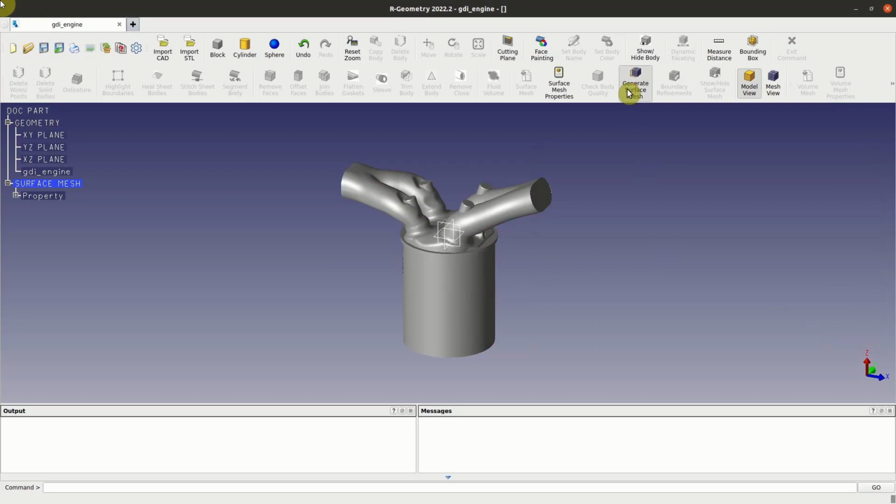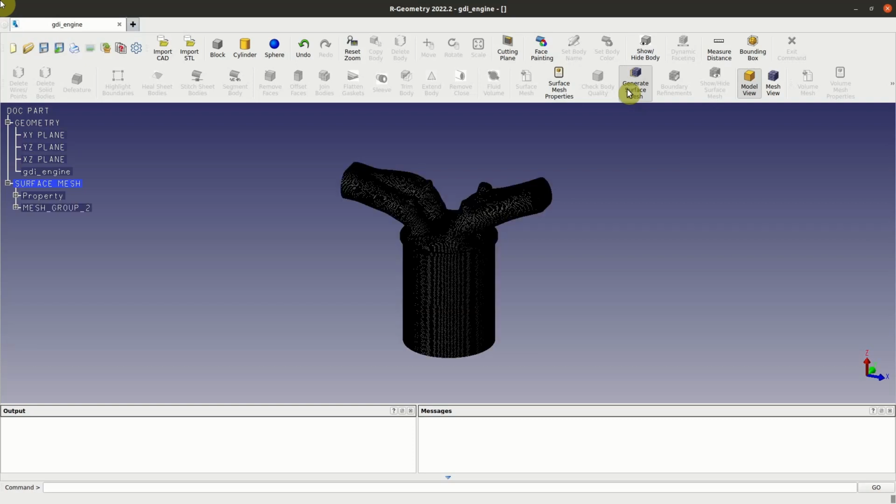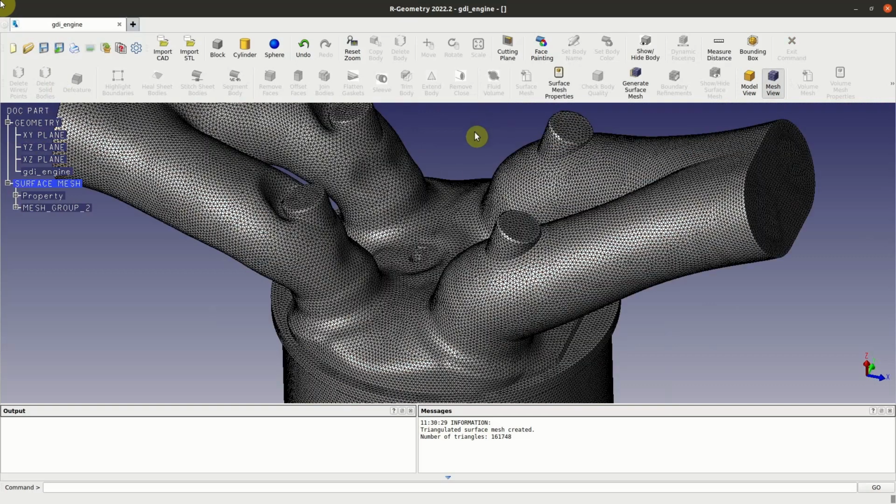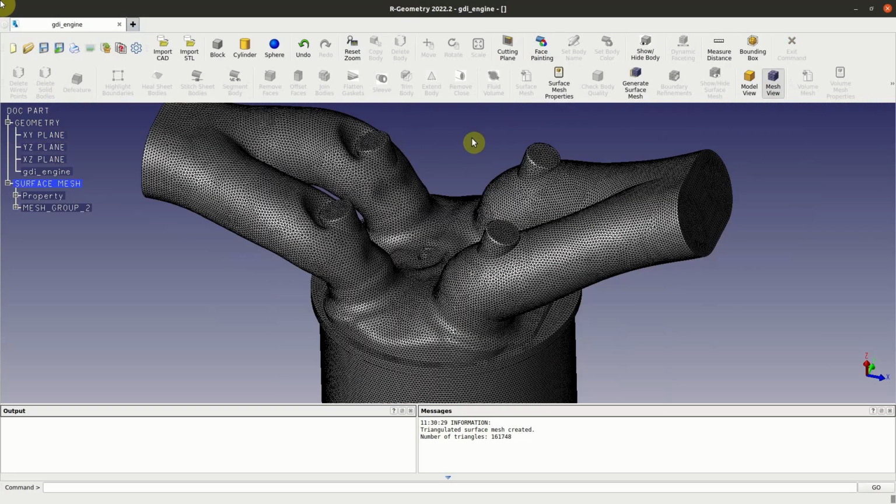The resulting mesh will be near isotropic with triangular cells and watertight, covering the whole body. It is used during the volume mesh generation to compute the intersection between the background grid and the surfaces, and so good quality mesh is needed for both static and moving surfaces. We can now save the session, and we can see the resulting grid, which is nice and isotropic.